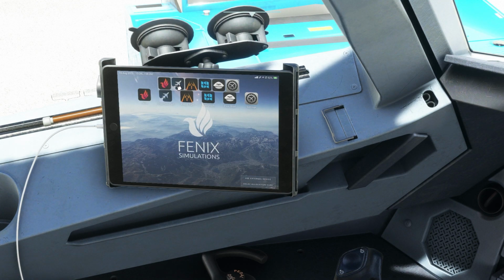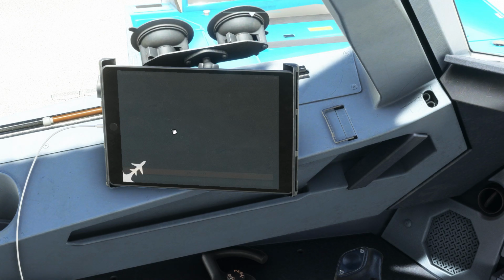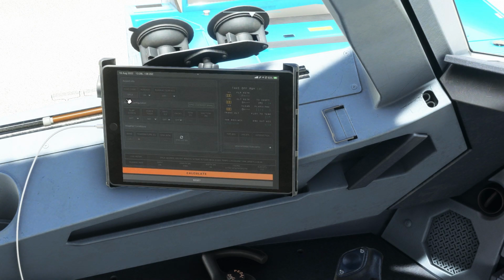So first of all, we have to go to the takeoff performance, and the airport code OPLA is automatically selected. For the runway, I'm going to use 36 right, because takeoff performance also takes into consideration the length of the runway. That's why you have to specify the runway. Runway surface is dry. Flaps, I will use 1+F, which is flap position 1. Force TOGA, yes. Now what is TOGA and what is flex temp? As you can see, this information is coming over here.